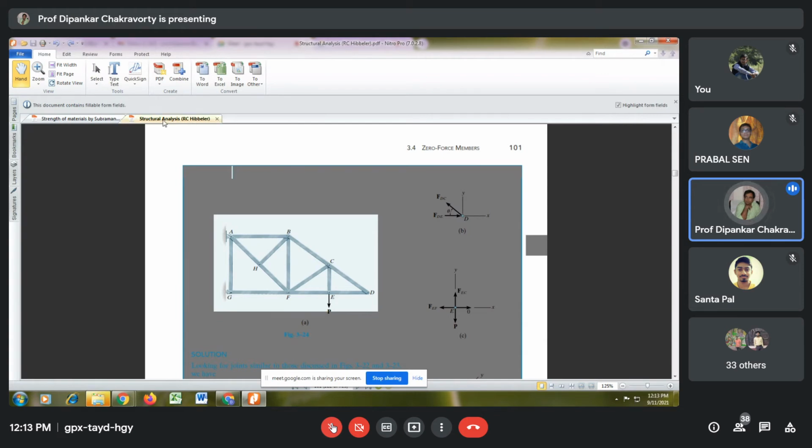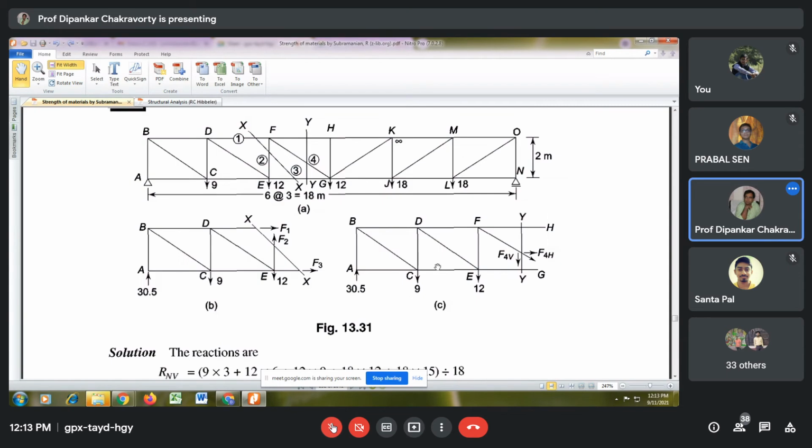So coming back to the method of sections, you know the reactions if AC has to be 0. Now if you want to get the bar forces in DF, FE and EG, you can pass a section X. It has cut 3 members.